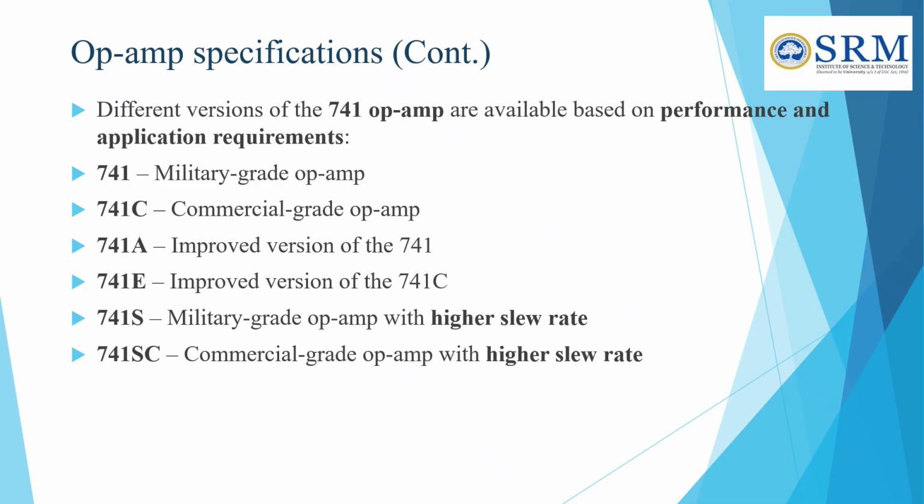The 741S and 741SC versions offer a high slew rate, meaning they can respond faster to changes in the input signal. Higher slew rate means the op-amp can handle fast changing signals more effectively. So depending on the application, whether it requires better accuracy, faster response, or wider temperature range, we choose the appropriate version.